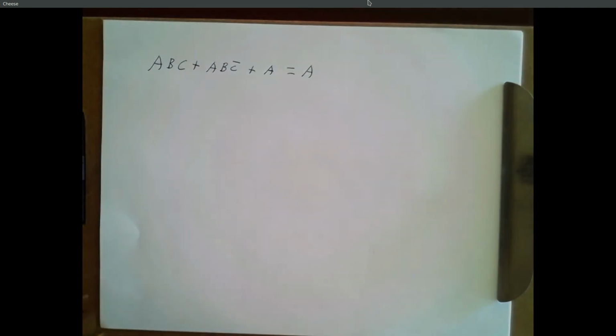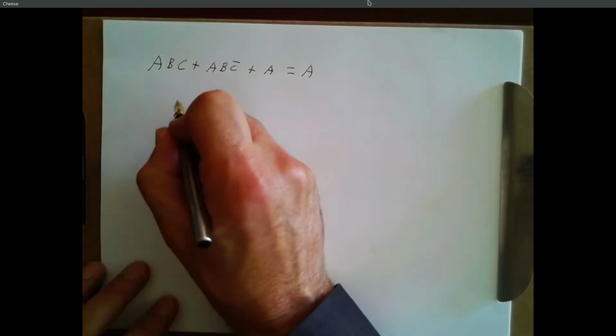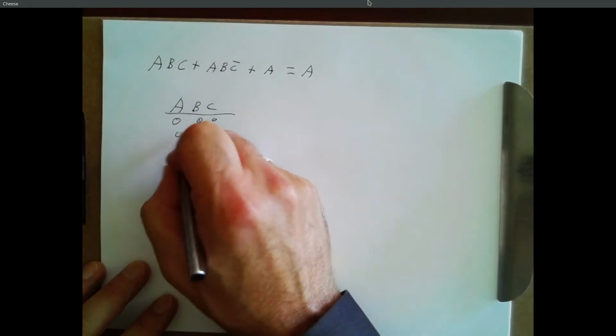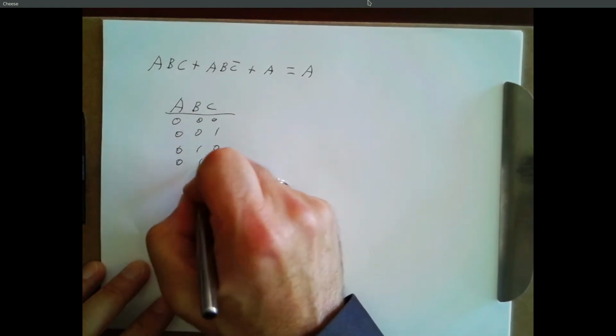The main way that we prove these things in this course is using truth tables. Sometimes you can prove these things using various rules of algebra. So De Morgan's theorem, distribution, commutativity, associativity, the adjacency theorem, all of these things from chapter 2 of the text. But we can also just prove these using truth tables. So you want to show something like this is true, make yourself a truth table, go through all the possible combinations.